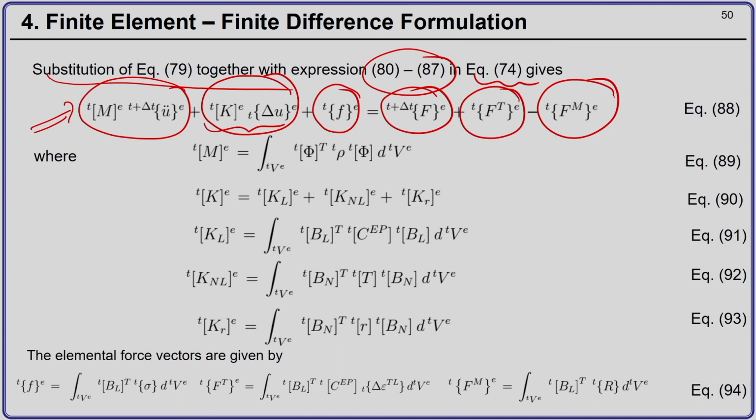Okay. So, remember, because this was already linearized, we are not getting mass into acceleration equal to net external force, we also have this tangent matrix times the incremental displacement. Okay. So, our objective is to find out this delta u, okay, and if we know this delta u, then we can compute this also here. Okay. So, we will see how we remove the time t plus delta t, u dot and u double dot also here.